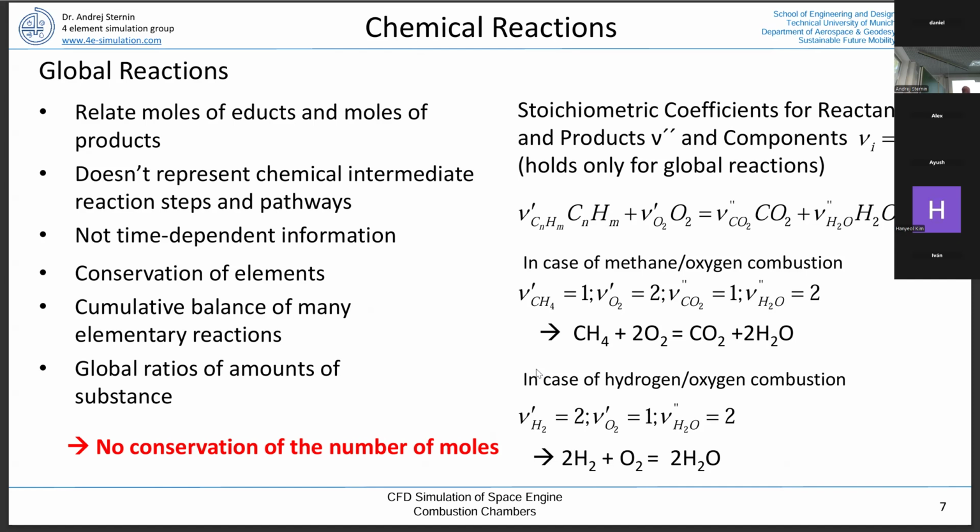So what we get is what is the input, for instance, any type of hydrocarbon fuel with oxygen, and we get carbon dioxide and water. Obviously, this is not telling us the total story because we have byproducts like NOx, or even some kind of unburned propellants such as CO. But that would be the global reaction in order to get an idea about what would be the necessary amount of input of fuel in order to generate a certain amount of power.